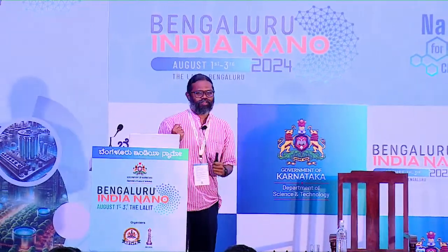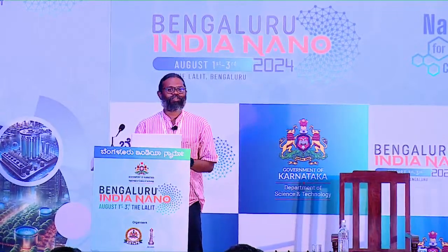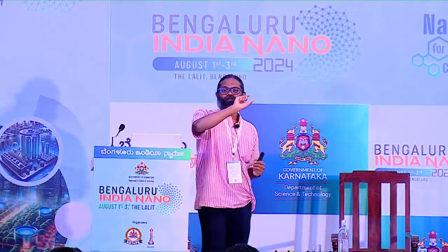Okay. But the question here is, okay, there is a source and drain here, and there is gate sitting here. It is polycrystalline silicon. It is important that the gate should have control over the channel. That means the gate should have very low resistance. Okay, and polycrystalline silicon is not known to have low resistance. It is better we change this polysilicon to a metal.